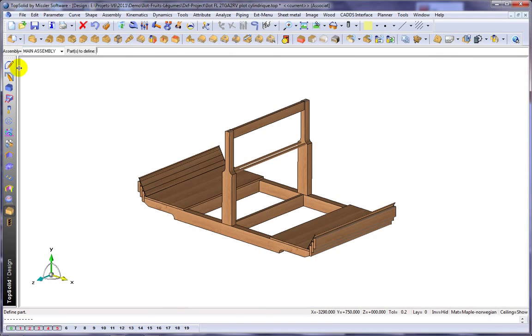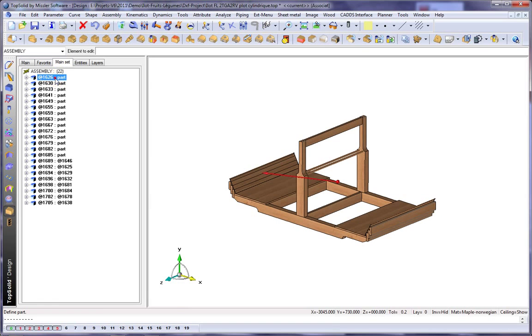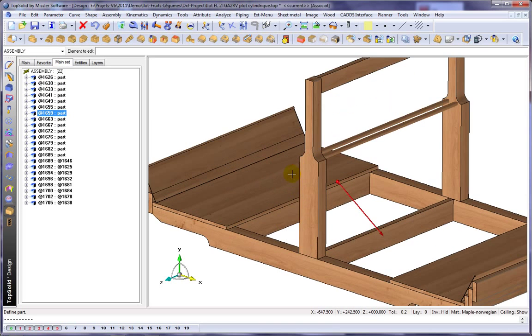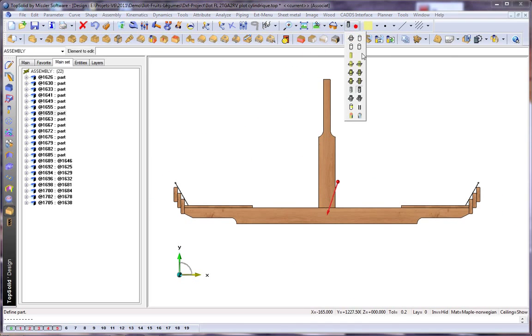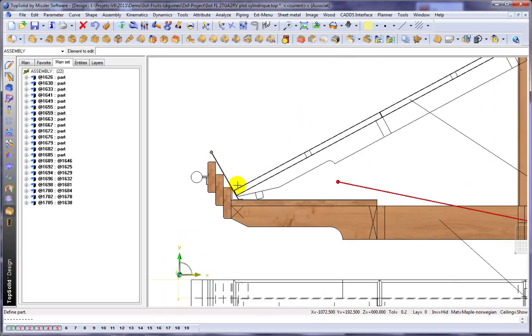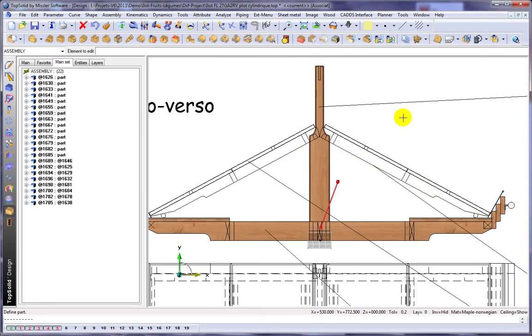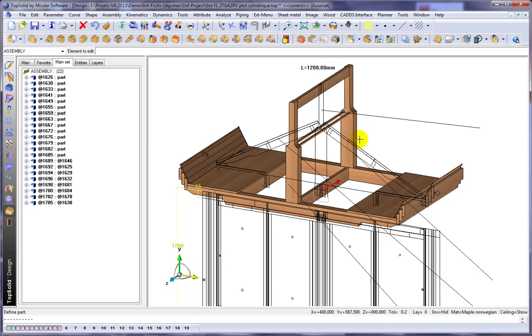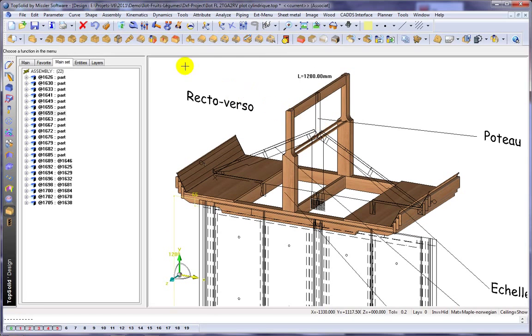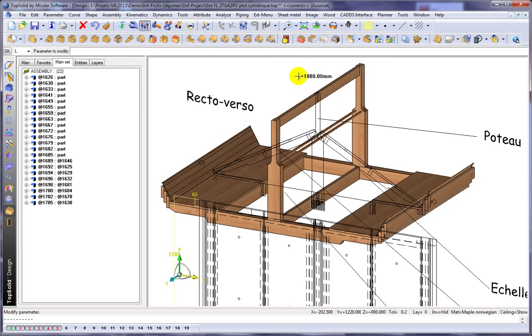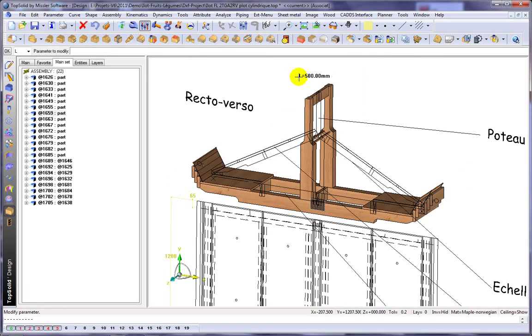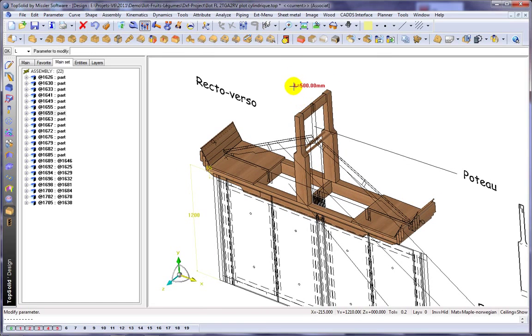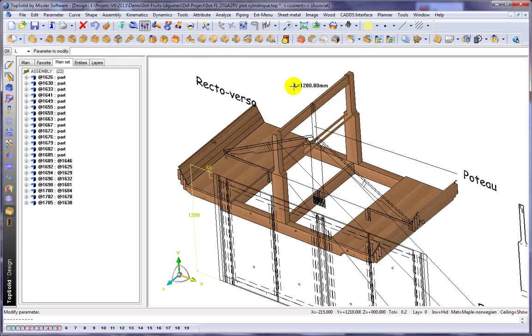And now, we're going to convert these all into wood parts so that we can create a bill of material of them down the road when we're ready to manufacture. So like that, you can see it inlaid over the 2D design. Everything's perfect. And then we can test it. Remember that parameter L? What happens if we make it 1800? And like that, everything's up to date. How about if we make it 500? You get the idea. We'll set it back to 1200.